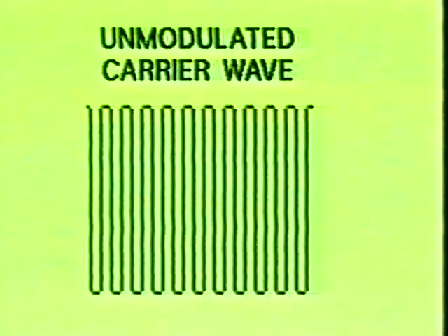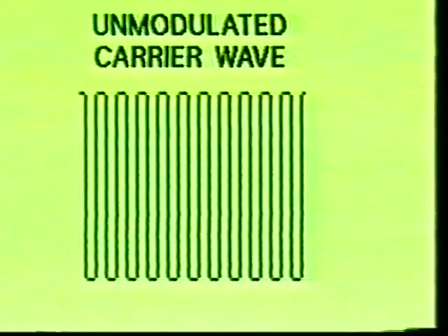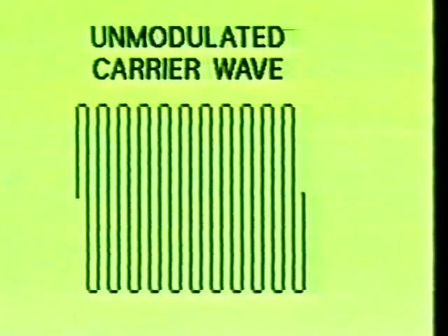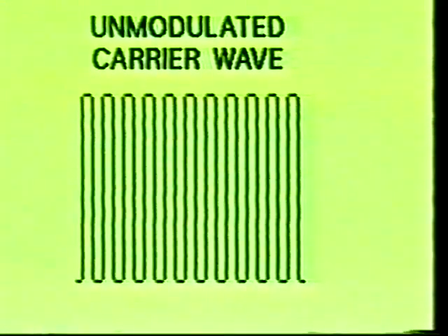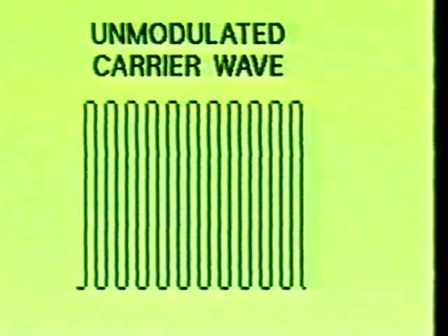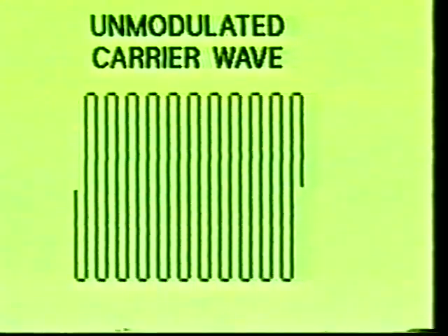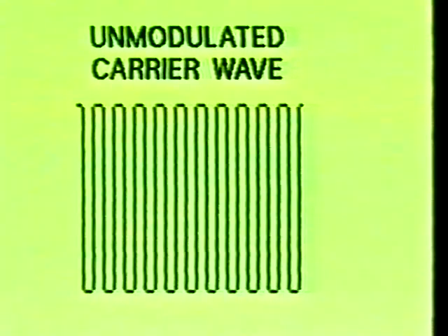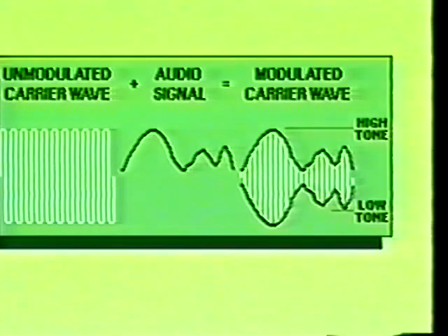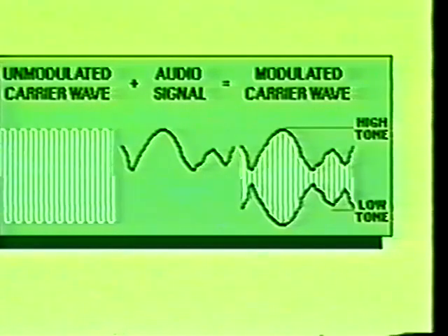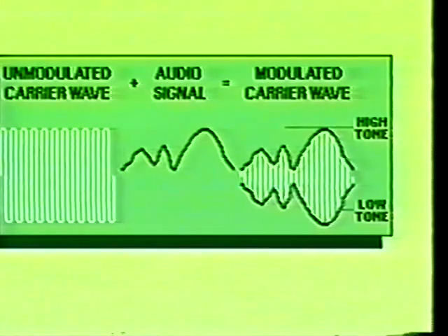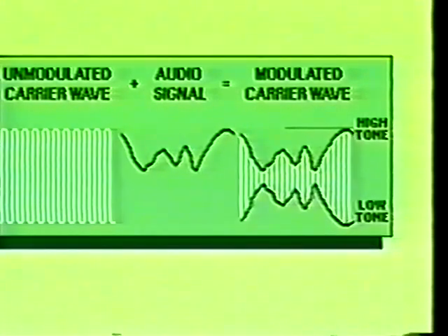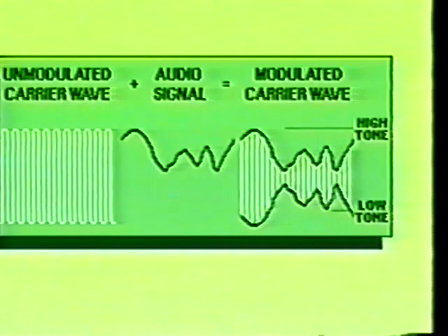In most practical modulation applications, the audio information to be transmitted must be carried through the air on a frequency greater than that of the audio frequency range. This signal is referred to as the carrier wave, and its frequency will generally be many thousand times higher than the audio frequency being transmitted. When the carrier wave is being modulated with the audio signal, the amount of amplitude modulation being produced will determine the frequency of the sound at the speaker of the receiver.